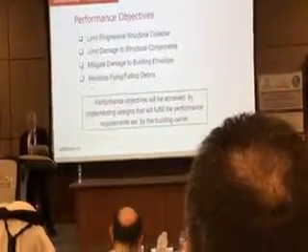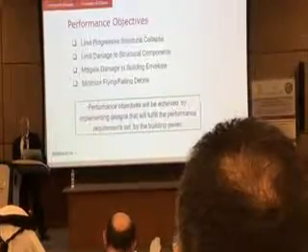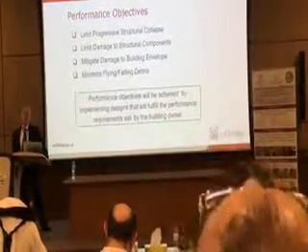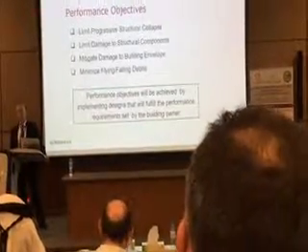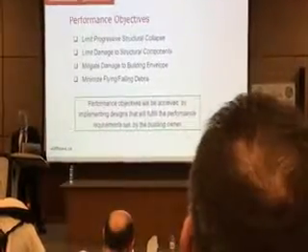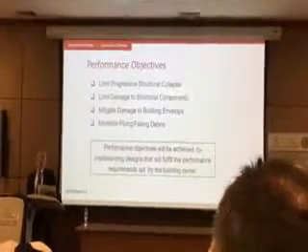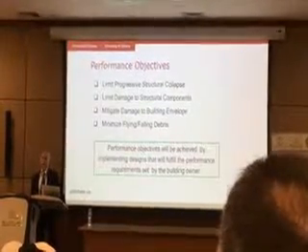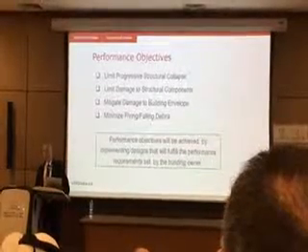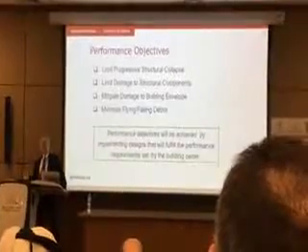You have to minimize damage to structural elements, and you have to mitigate damage to the building envelope. Although some structural elements have collapsed in the past, as in the case of the Oklahoma City bombing, the World Trade Center, and the New York parking garage bombing, most of the time the threats are to non-structural elements, the building envelope, because masonry walls collapse.